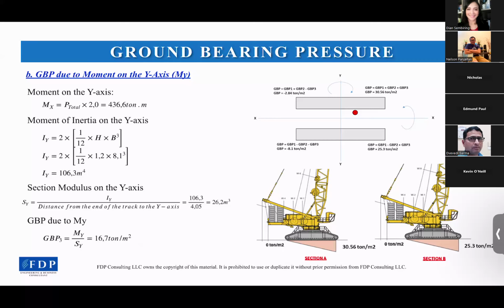Any other question? Yeah, Edmund, I just want to add some information, like what Nelson said before. If you get geotech people involved with your heavy lifting operation to identify your soil, you will get the soil type for your operation, whether there is groundwater depth, and also the bearing capacity and strength of your soil.